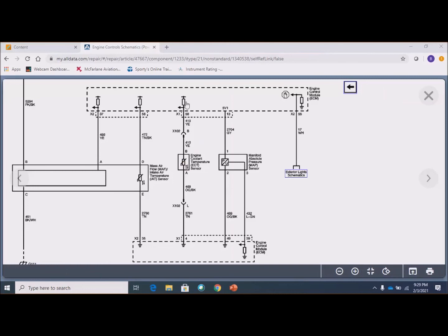So what's happening is, going back to your basic electrical, if you have a series circuit and you have two identical resistors, so if this one and this one are both, say, 33 k ohms, then the voltage drop on each of them will be identical. So if I give this 5 volts here, then at this point right here, I'm going to have 2.5, because this resistor here and this resistor here will drop identical amounts. They'll each drop half of it.